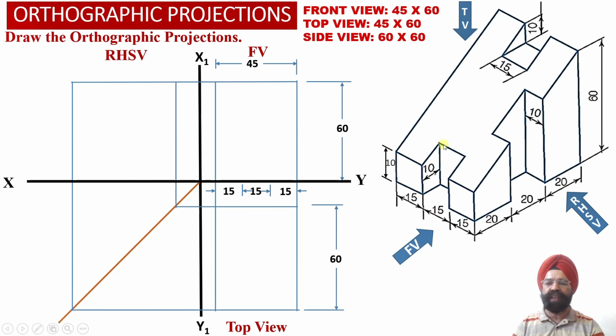Similarly, corresponding to the third slot, here we have been provided with the depth of this slot as 10 millimeter. Then the width of the slot has been provided to us as 15 millimeter. But we have not been provided with information regarding the height of this vertical edge of the slot over here. So in this case, we have to proceed by drawing various dimensions into the different orthographic views in order to obtain complete information regarding these three slots which are available with us in this inclined truncated rectangular prism over here.